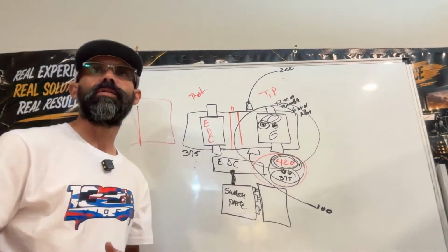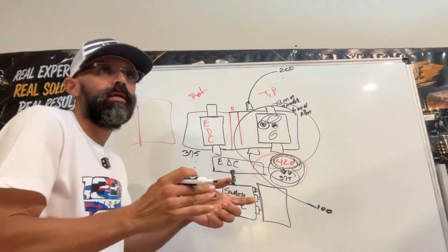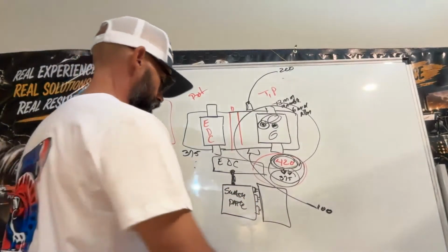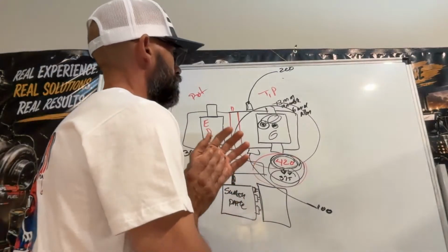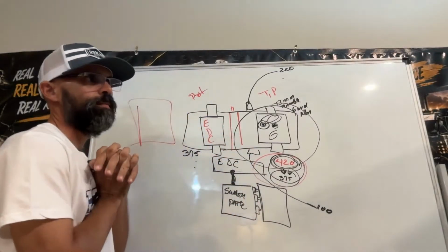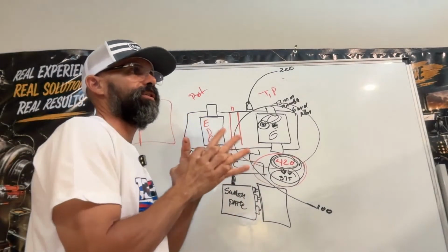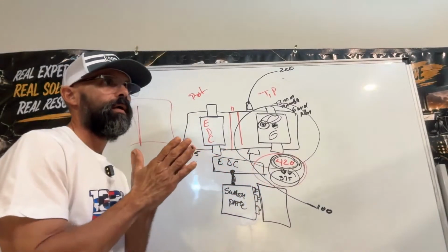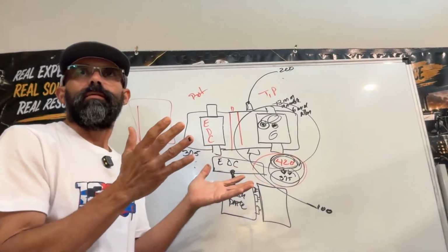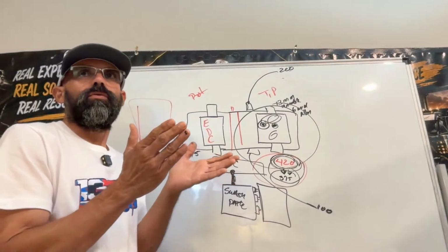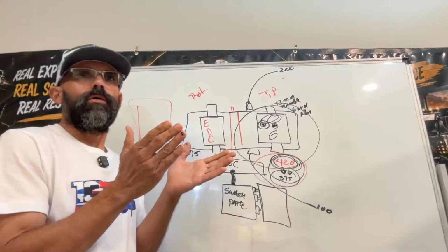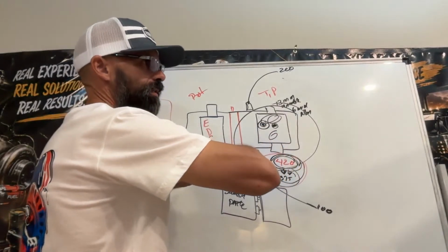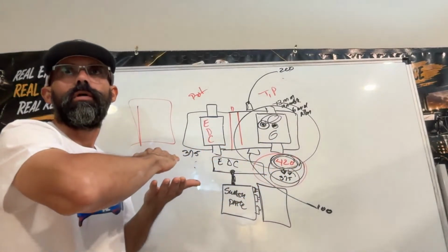Doesn't mean that the pump is bad. No, just tweaking it, adjusting it. That's all you gotta do. But it's simple, you know. It's simple. If your carriage or machine is moving by itself, all you gotta do is adjust it because it's out of neutral. The swash plate, it's stroking, it's sending pressure, and that pressure gotta go somewhere, right?